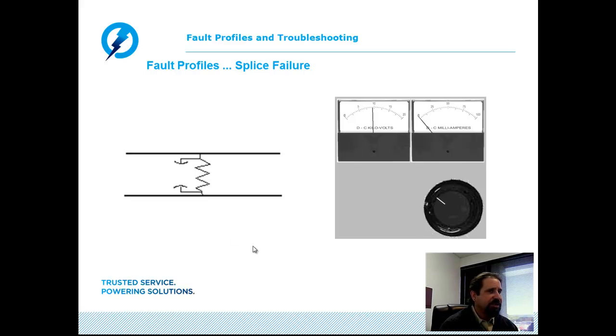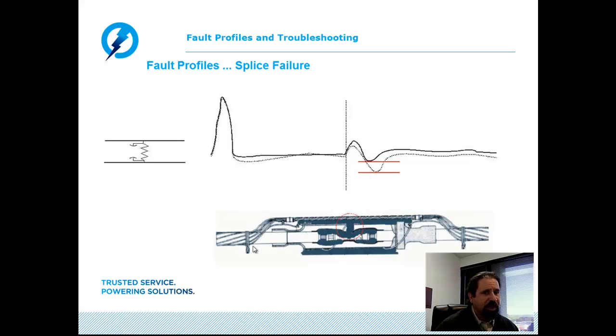Now, if we were using the time domain reflectometry techniques, a splice has a very distinctive signature. When we look at a splice on your average pulse echo waveform, what we will typically see is an upward reflection as the radar pulse enters the splice, and then a negative reflection as the radar pulse leaves the splice. So once we start to learn that pattern, we can put these clues together.